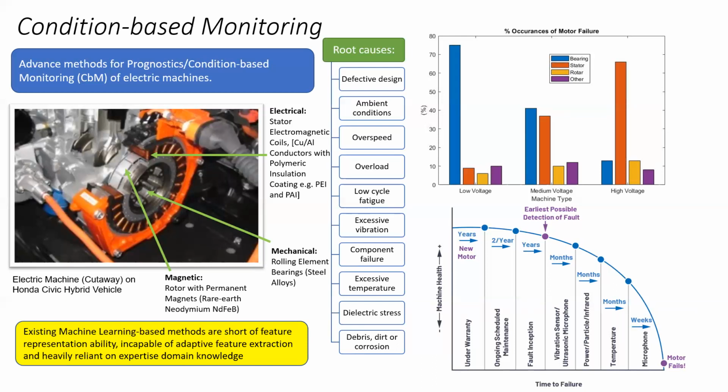Data acquired from various sensor types can be used to calculate the time left before failure occurs. This time is also known as the remaining useful life of a component. Knowing this time means the health state of a machine can be predicted so that suitable maintenance can be carried out at the optimal time.